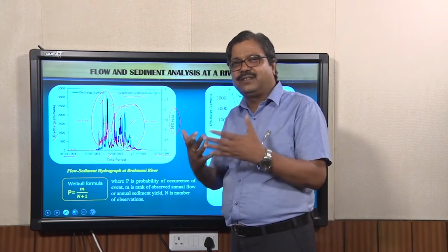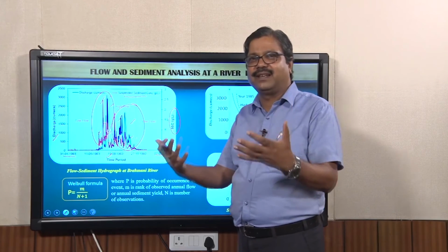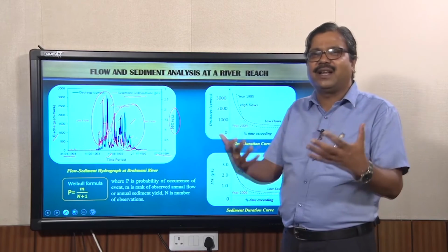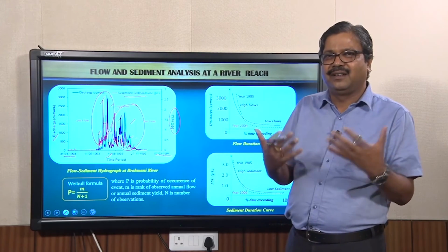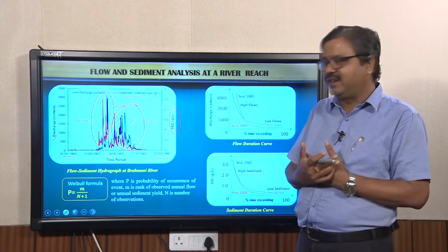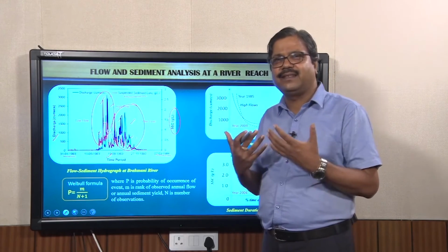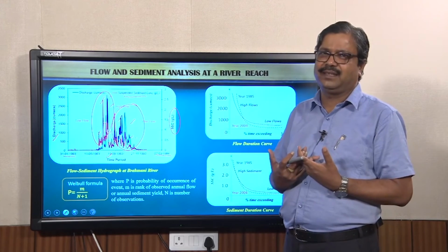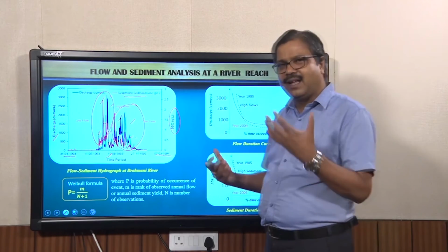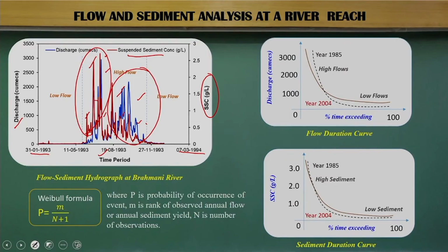We draw first the flow hydrograph and the sediment hydrographs, and we try to analyze how things are happening visually. First try to understand it, then we go for a simple flow duration and sediment duration curve analysis. What do we do? As you know from hydrology books,